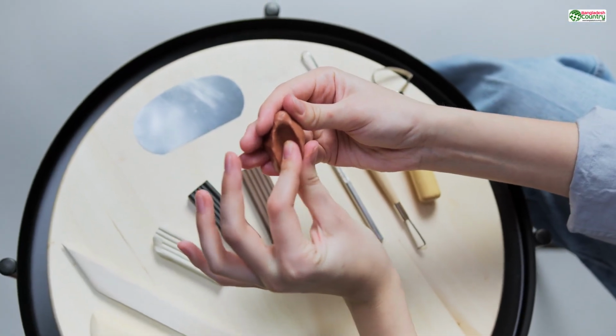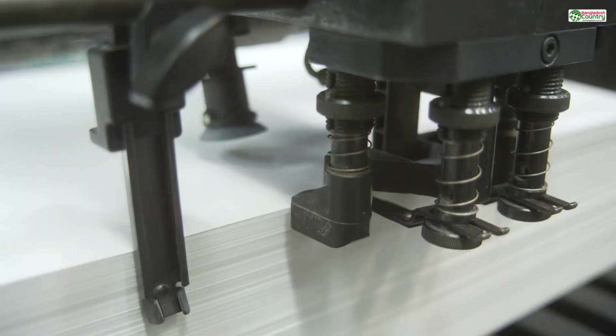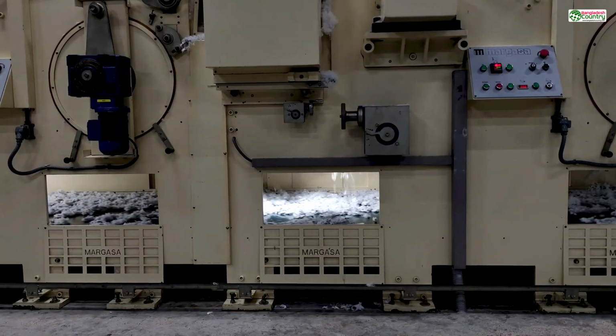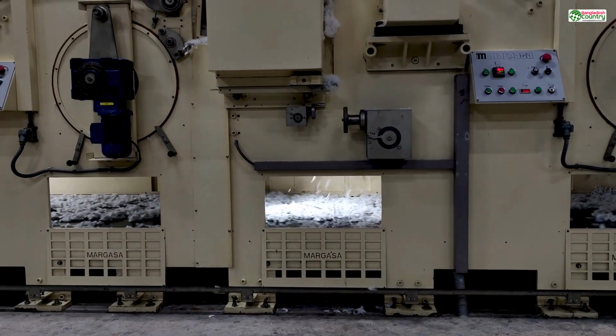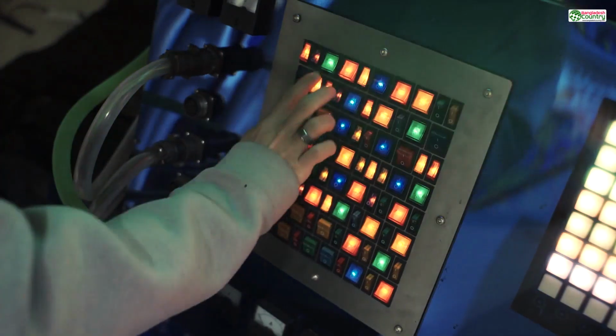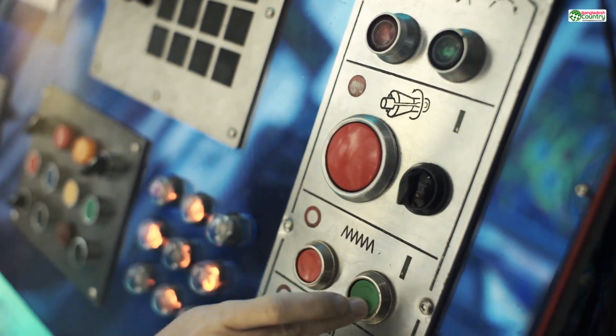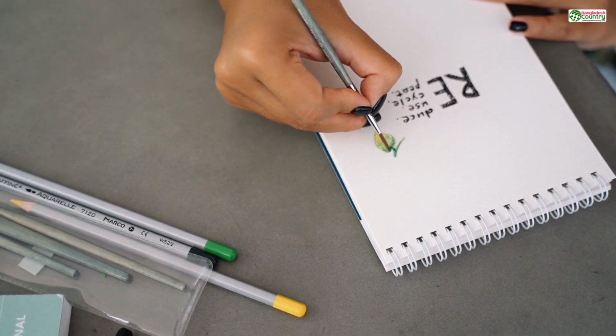Online printing services are smart, but they're not always perfect. Their automated orientation tools aim for a good result, but they don't know which surfaces are most important to you. By taking control of the orientation yourself, you are directly controlling the outcome. You can often reduce your quote from an online service by 10, 20, even 30% or more, just by finding the cleverest way to position your part to minimize or eliminate supports.